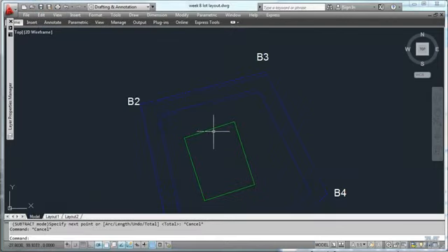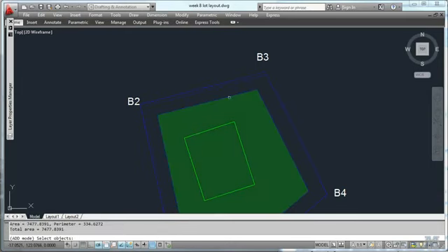And what we'll want to do is figure out the difference between these two things. So let's use the measure geometry again with area. And let's see, we want to add an area. We'll add an object. I need to type object. We're going to take that section right there. So there's an add. Now let's subtract. And we'll also do an object. Subtract mode and subtract the building out of that. And then I think that should do it.